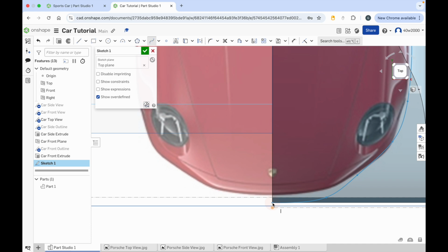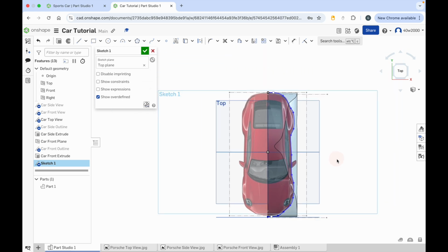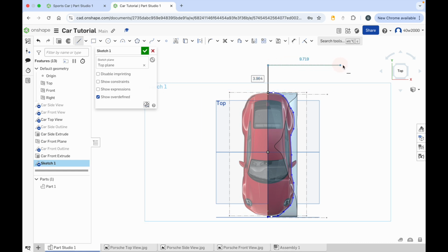Okay, so when you've done that, you can zoom back out. And if you move the mouse cursor, it'll want to keep going with that extrusion. Press the escape key once to cancel that, and the escape key again to come out of the spline tool altogether. Now we're going to use that same technique as before. Click on the line tool, go to the first point of your spline, click once, move the mouse cursor vertically up, and then move it to the right, down, again vertically, move along to that center point, and you can see it kind of snaps to that center point. You see the orange guideline appear.